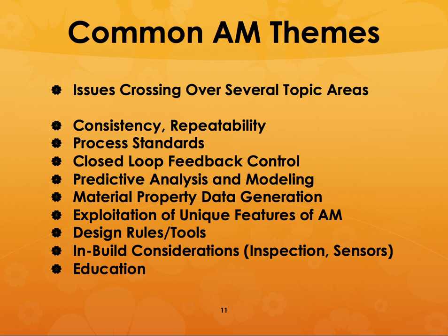So for example, if you know that it is stronger in the X and Y direction, can you make that X and Y direction the Z direction? Can you lay down the part such that the X and Y direction actually now becomes the Z direction so that your part becomes extremely strong? Or if you have a robotic arm, you first lay down the part in the X and Y direction, then the robotic arm comes and turns it over, and now the head feeds the material in the Z direction so that you have better properties in the Z direction.